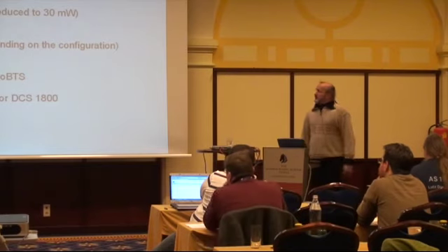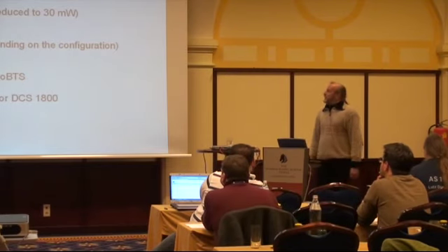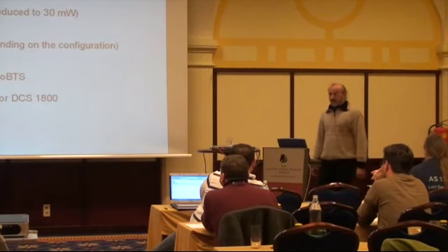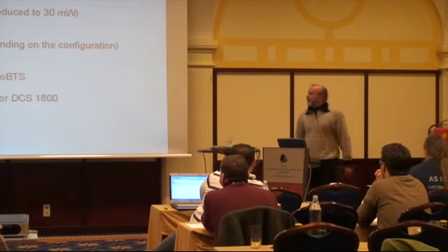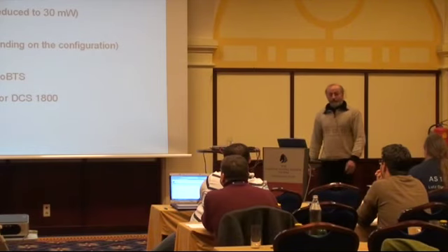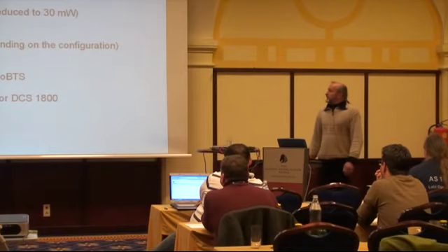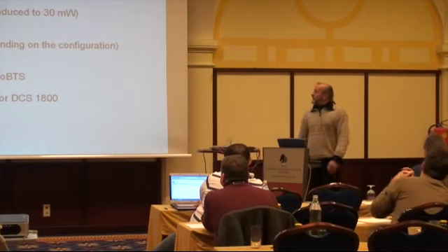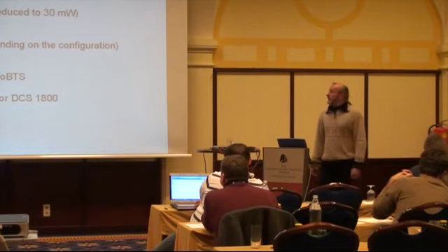The second base transceiver station supported by OpenBSC is the Nano BTS from IP Access. This is a rather current unit. It's available in several configurations and for several GSM bands. The output power of, for example, the 1800 megahertz device is 200 milliwatt.